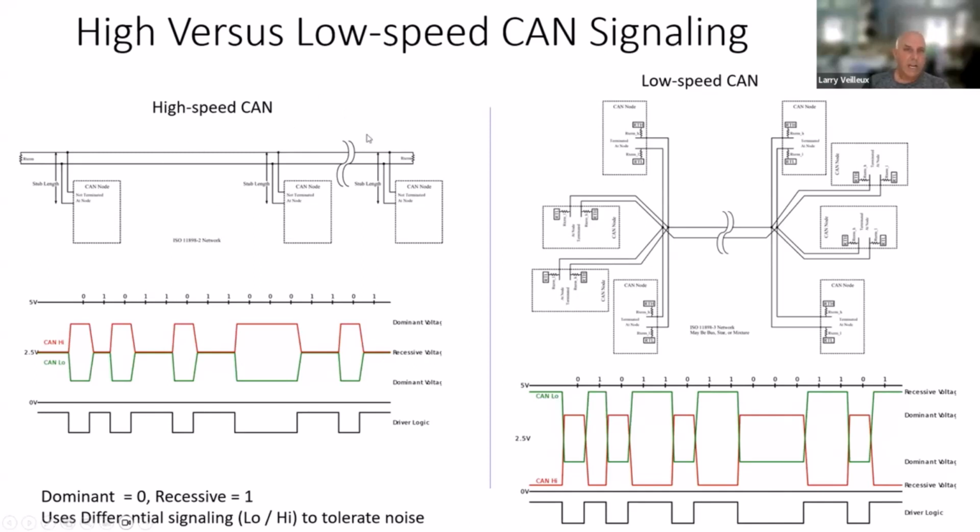And what's not depicted here, which I haven't mentioned yet, is that these are twisted together. Part of the reason for twisting them is to hold them together. But the other part is that it also helps with noise immunity because it keeps the cables close enough together. So when a voltage spike from whatever, it could be from your cell phone ringing or something like that, induces a voltage because it's not shielded wires. It's possible, but let's say you get a 0.5 voltage induced in this twisted pair. Well, both CAN high and CAN low are going to go up by that 0.5.